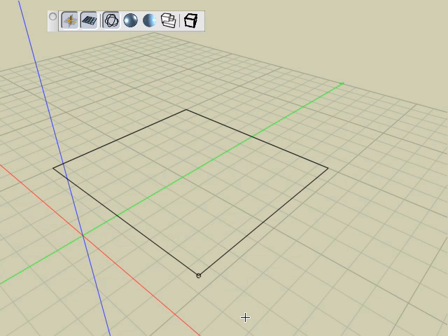With the Set First Point tool active, click on the point you want to make the first point. Why would you want to move the first point? Well, because its position affects some operations. For example, when lofting between a number of shapes, it is important that the first point of these shapes line up. Otherwise, a twisted object will be generated.